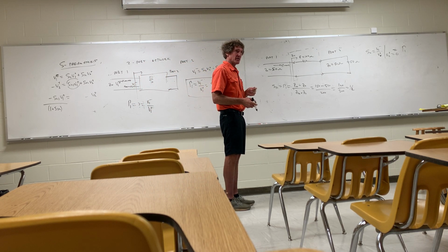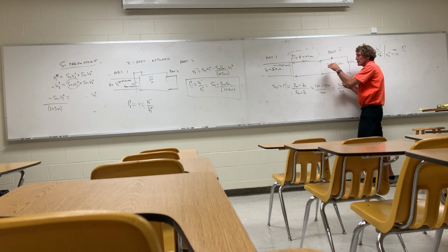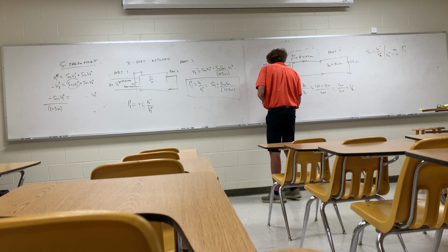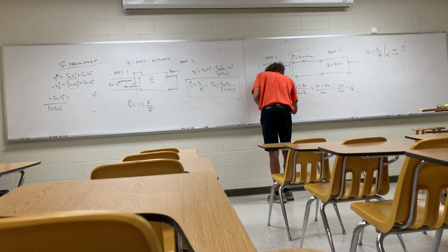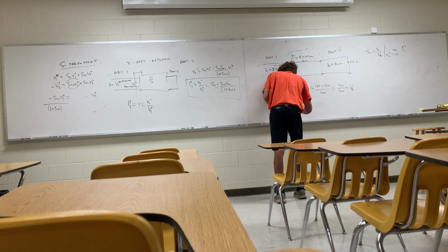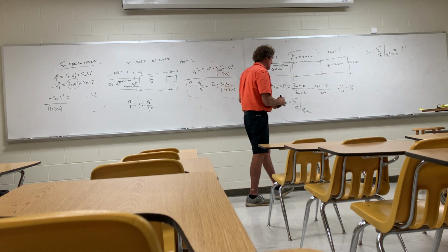By the way, how many people see this? If I want the reflection coefficient at port 2, this network looks exactly the same. Just spin it around, right? It's a symmetric network. Do you see this? Wouldn't it be the same too? It would. When I look at S22, that's equal to the reflection coefficient of port 2, which would be V2 minus over V2 plus, assuming V1 plus is 0. Just throw that matching condition over here, and it will be exactly the same, 1/2.